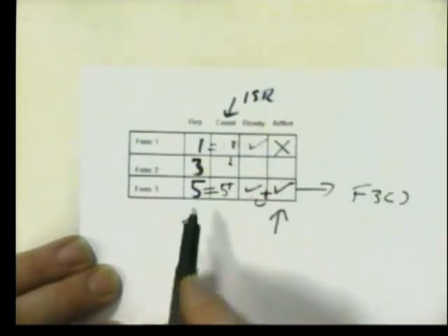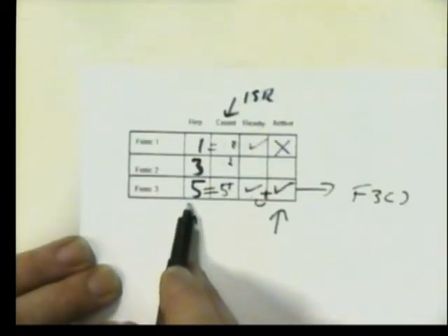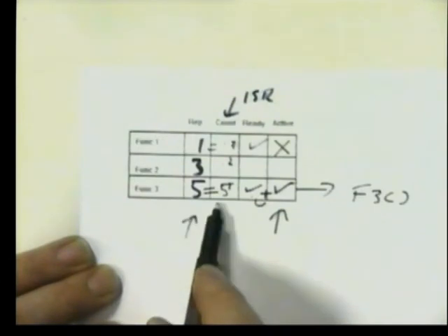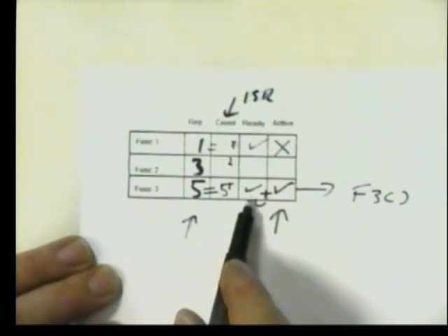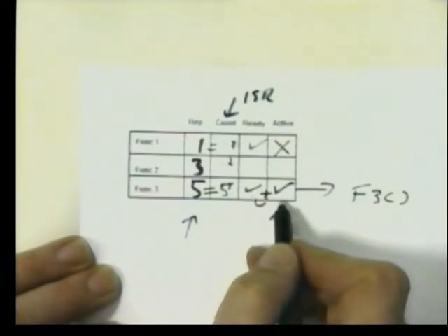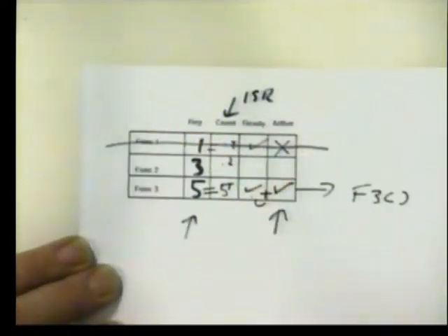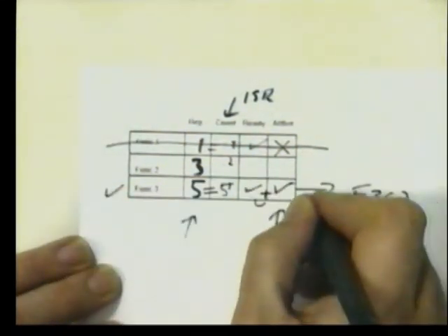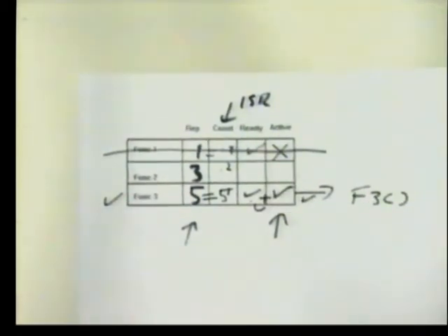So we have the ability to set different execution times. This is the field used by the ISR. Functions are signaled to be ready, and we have an activity flag which allows us to kill off. In this case, we killed off function 1, but we left function 3 alive.